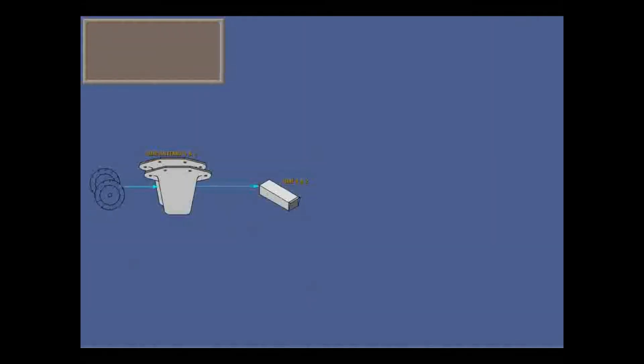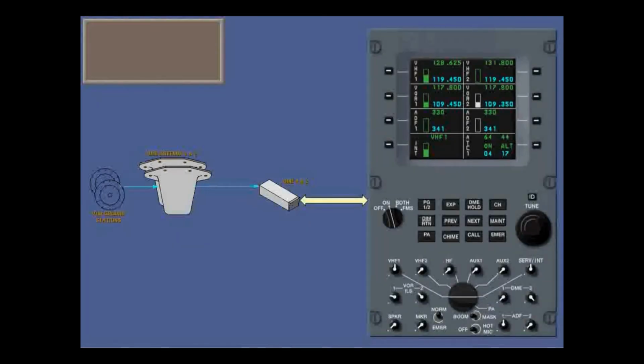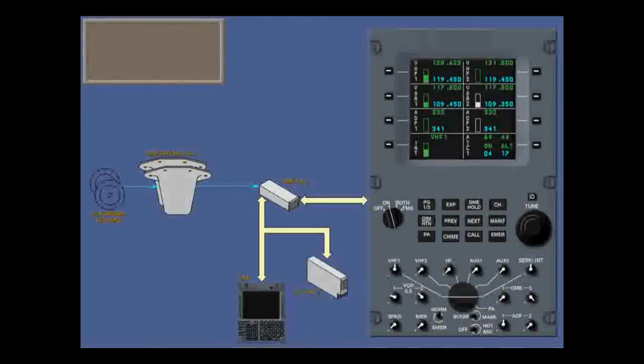Distance measuring equipment, DME receivers 1 and 2, function independently and continuously to supply slant range distance to a DME equipped ground station by measuring the time for a signal to travel to the station and back. Tuning and selecting a VOR or ILS frequency on the ARC2 automatically selects its paired DME frequency. The DME system also supplies data from multiple ground stations to the FMS to calculate its position fixing algorithm. It also feeds into the ATC transponder system and into TCAS.